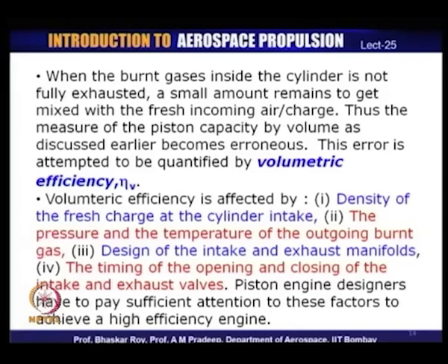Now, volumetric efficiency we shall define in a minute, but let us quickly understand what it is all about. The density of the fresh charge affects the volumetric efficiency, and we have seen that in an aircraft engine we need to increase this density through the process of supercharging.